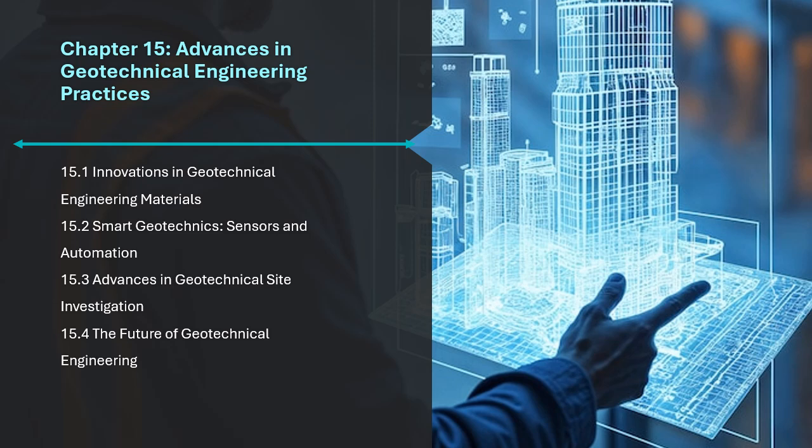Geofoam. Geofoam is a lightweight, rigid foam material used for lightweight fill in areas with weak soils. Recent advancements have improved the thermal insulation properties of geofoam, making it an attractive option for use in geotechnical applications in cold climates or where thermal insulation is critical.